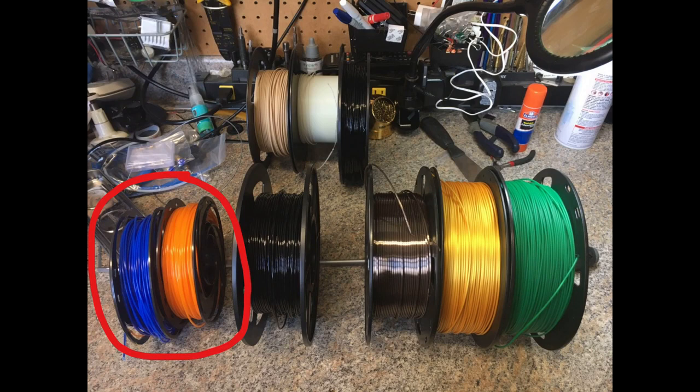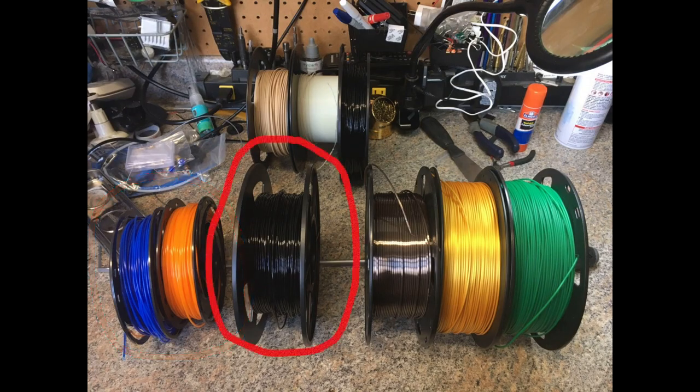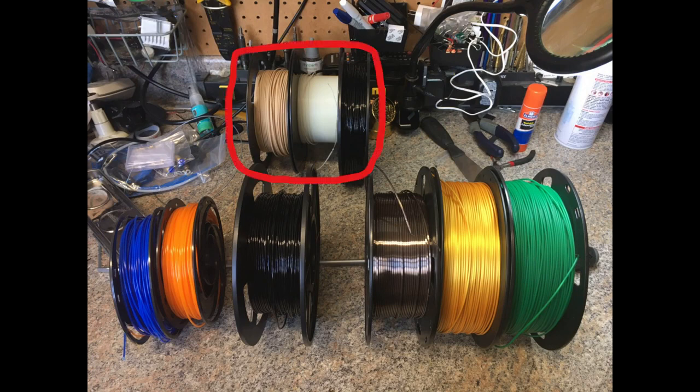If your house gets very humid in the summer, you may need a dehumidifier in order to print with this filament. Finally, PETG is the happy medium between PLA and ABS plastics. It requires more heat than PLA, but not as hot of a print surface as ABS. It is a stronger material than PLA, yet is more prone to stringing. While PLA, ABS, and PETG are the most common, there is a wide range of filaments you can buy. Glow-in-the-dark, metallic, and wood variants of PLA filament can be purchased, as well as TPU phone case material.